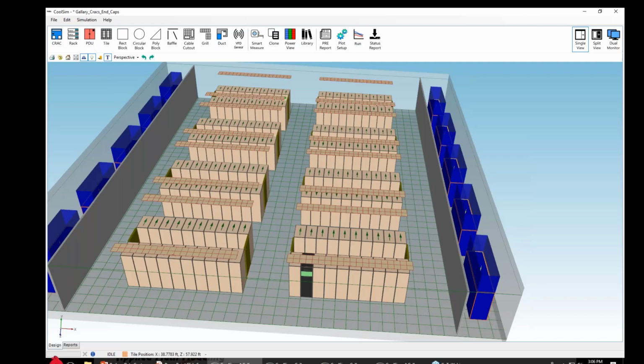Now, having said that, it's a cost issue because it's cheaper to put one pressure sensor under the floor than it is to put 3 temperature sensors, one per rack. That cost adds up quick. But from a control point of view, it's a better control because you're actually measuring what it is you're trying to control, and that's rack inlet temperature.